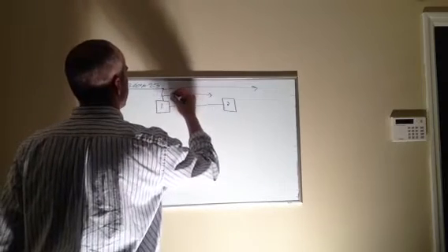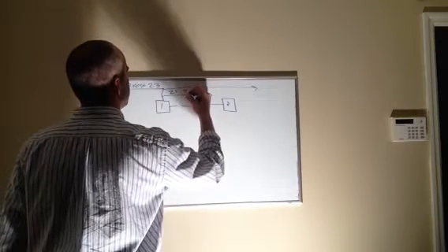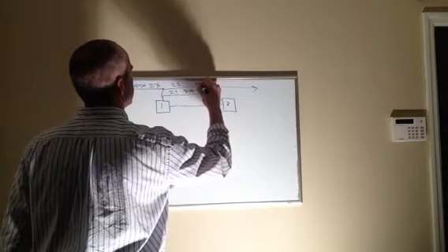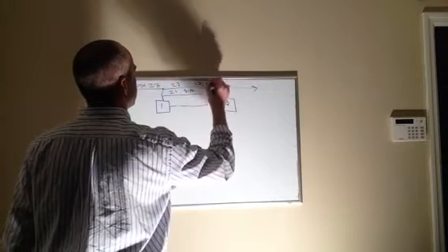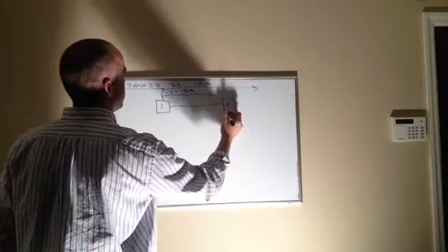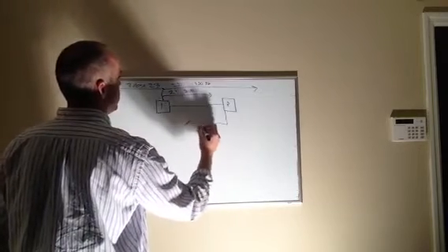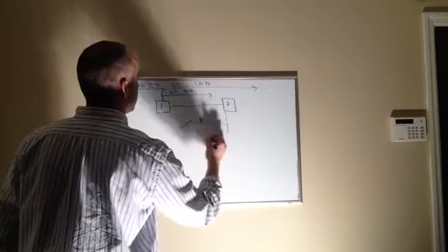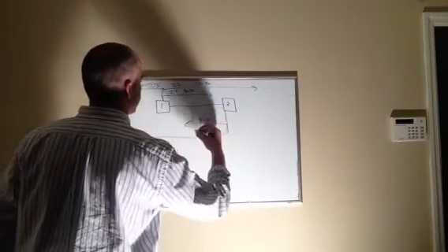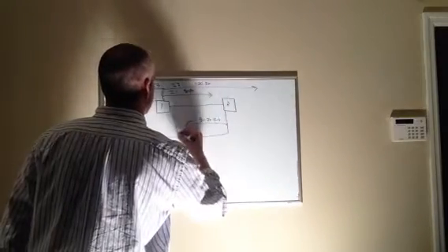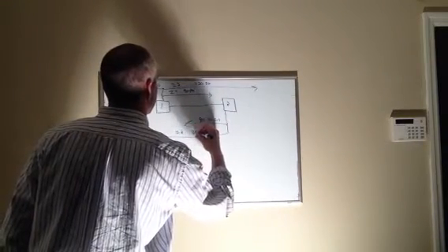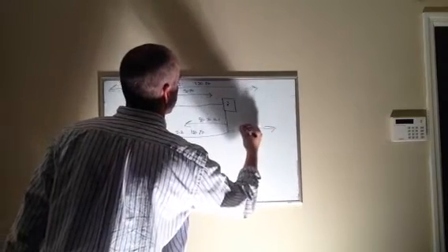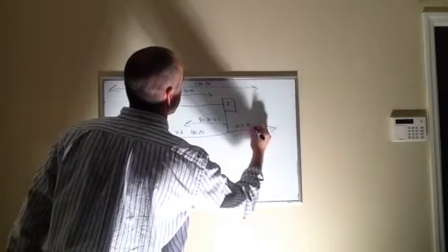Same thing at the other end: zone 1, 90%, zone 2, 120%, zone 3, reverse looking 300%.